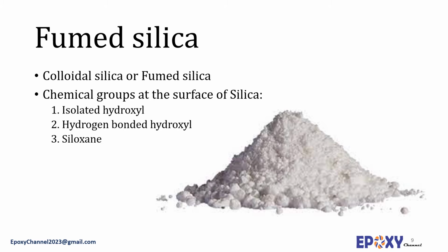The hydrophilic silica is most effective in nonpolar and medium polar media. The performance of hydrophilic fumed silica is often improved by adding a polar substance such as ethylene glycol, glycerin, or some secondary amine to the formulation. In medium polar to polar media, hydrophobic fumed silica is a more effective thickening agent and generally preferred. Hydrophobic fumed silica is also noted for providing superior moisture resistance in adhesives, sealants, and coatings.